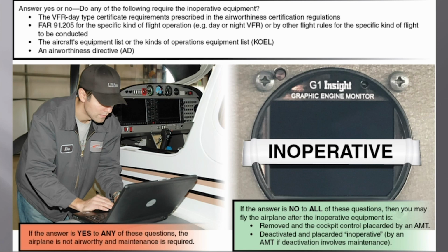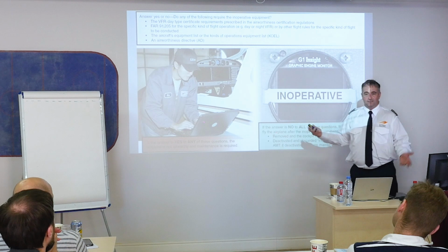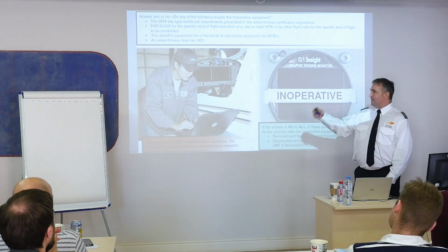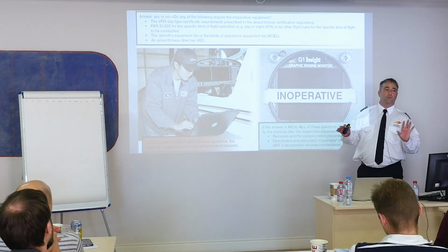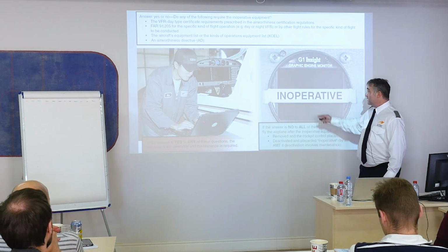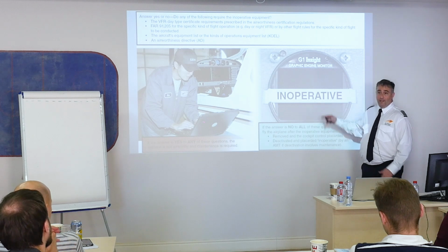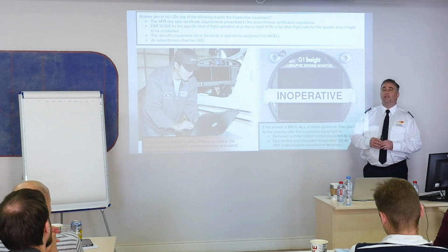Remember I told you guys I'm kind of a real person. Okay. You won't find all of the inoperative stuff placarded inop on any airplane, no matter where you are. That doesn't mean that that's right, but what I'm saying is, before you cancel the flight altogether, go tell somebody, try to work on getting that fixed, but if it's just not working, well, it's just not working, okay? Yes, I understand, we're supposed to report it to maintenance, we're supposed to put it inop, but don't be terribly surprised if you find one that's not placarded. Because it probably was placarded inop, and then somebody else got in there and pulled the sticker off. That's what we run into, that kind of stuff.